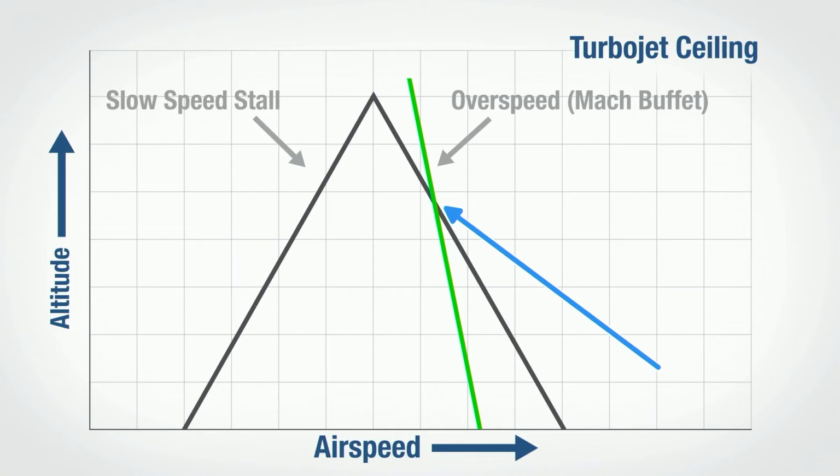So at some point at cruise altitude, there's still enough thrust left on older aircraft to get past their maximum Mach number, possibly in level flight. Those airplanes are capable of flying in Coffin Corner. They've got enough power at high altitudes where they could exceed, again, not necessarily the speed of sound, but they could get critical Mach, they could get supersonic flow somewhere on the airplane. And that typically would only happen in high altitude cruise.